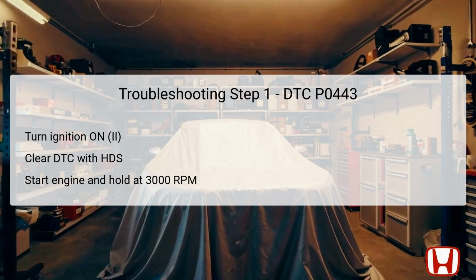If DTC P0443 reappears, the failure is confirmed, and you'll proceed to the next step. If not, intermittent issues may be present, and inspecting connections would be warranted. In the second troubleshooting step, you want to determine the specific failure type related to the EVAP Canister Purge valve.